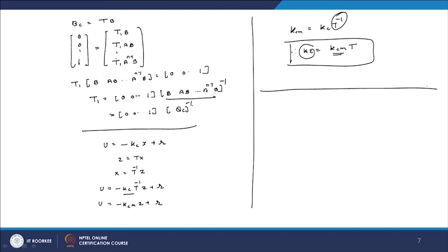Now we know that the eigenvalues are invariant after doing transformations. We have seen that the given system matrix can be converted into diagonal form, and then we have seen the Jordan form. So different forms are there, but eigenvalues cannot change. Here also, after doing the transformation, eigenvalues cannot change. When the eigenvalues cannot change, it means the property of the system cannot change. Therefore, we assume that we have a desired eigenvalue.